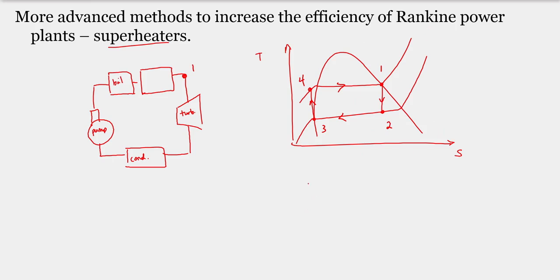Now, remember what we talked about last time. For my Rankine cycle, I said we could approximate the cycle efficiency as being 1 minus the temperature at which we reject heat, divided by the average temperature at which we add heat. So I want to operate out here in the superheat region because it's better for the durability of my turbine. And if we look at this number here, T in average is defined by these limits here for the basic Rankine power plant.